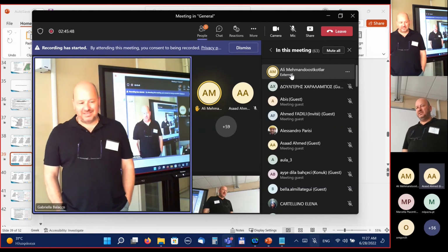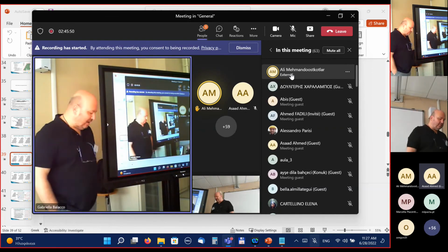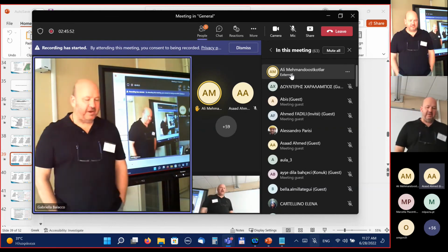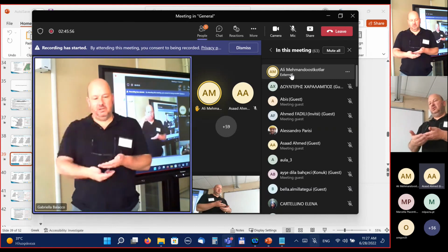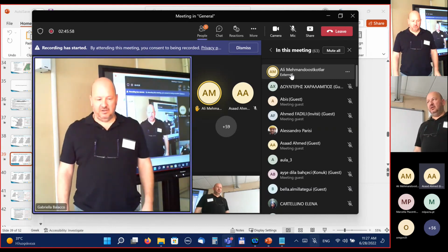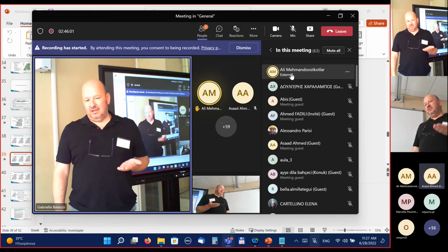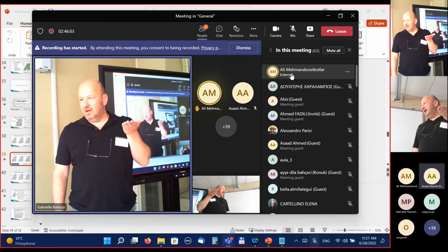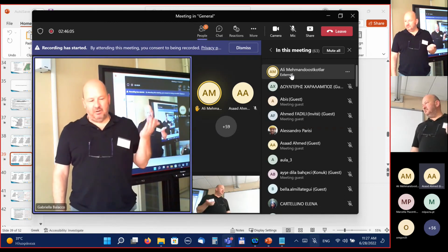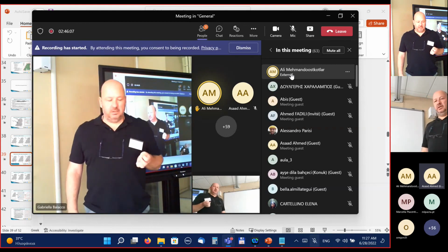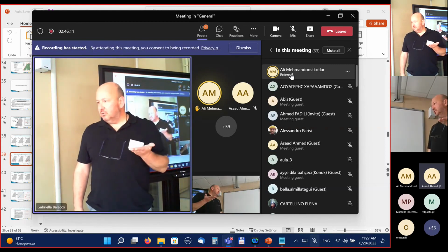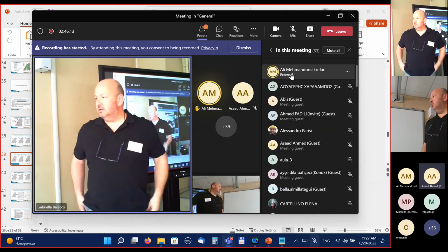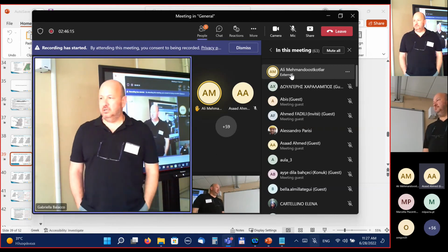In this case, we should have other options, for example, a free drainage option from the bottom of your soil model, the vadose zone. But if the water level of the unconfined aquifer is quite high, let's say a couple of meters from the soil, then you can use it as a boundary condition for the vadose zone model.